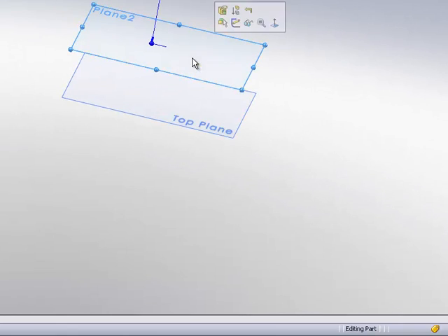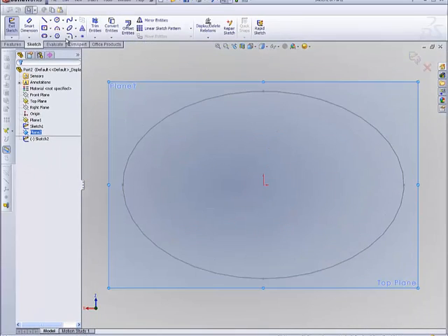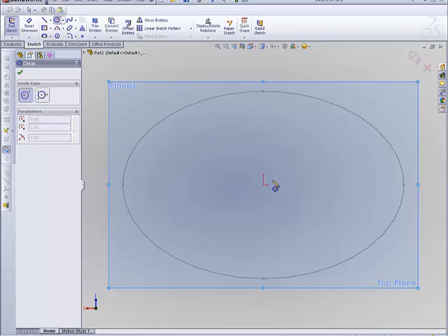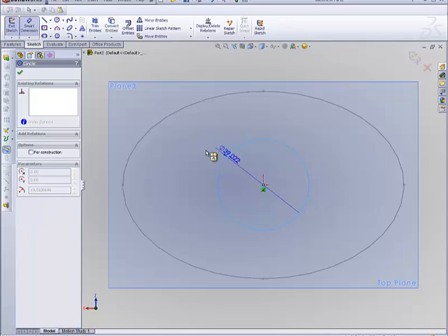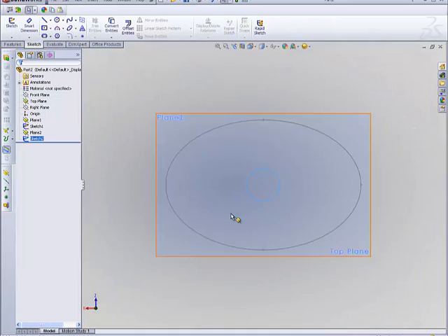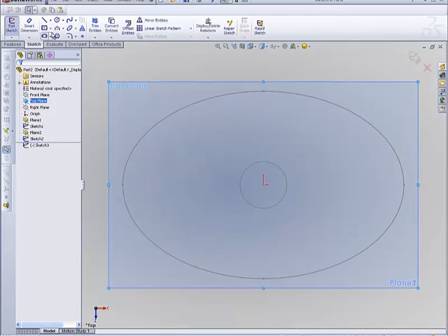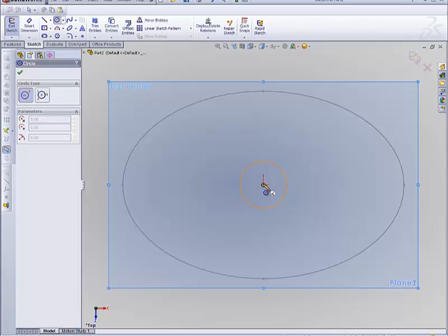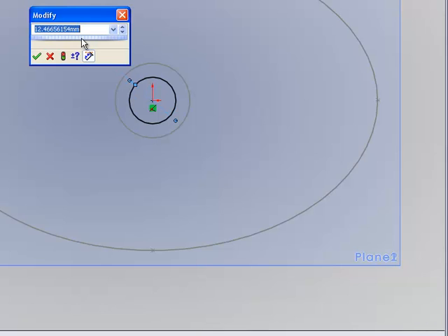Now this is where we want it, and this is a neat trick because showing our dimensions, we need a 20mm circle right here. So click sketch again, do the normal 2, and just do a circle. Smart dimension it to 20, and exit sketch. So, and then for the final one, do sketch, normal 2, circle, and this one will be 10. Bada bing, bada boom, done.